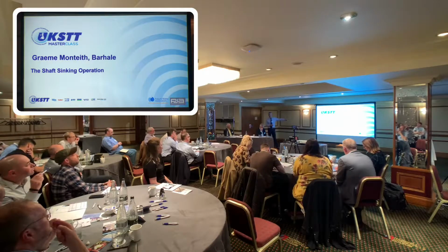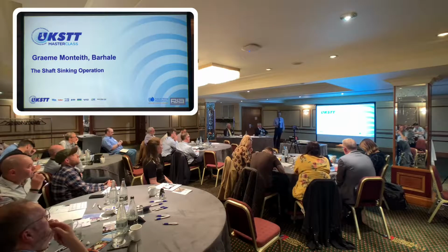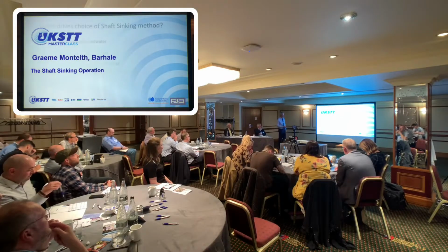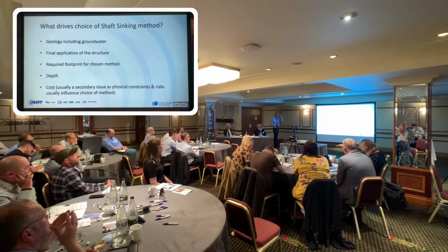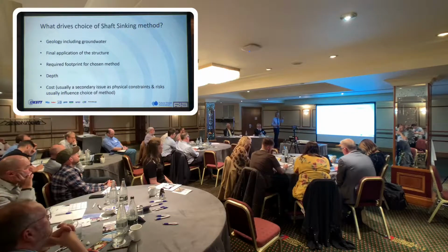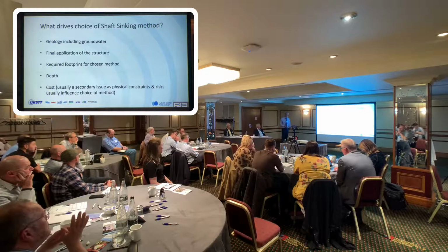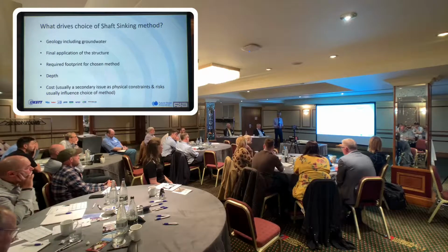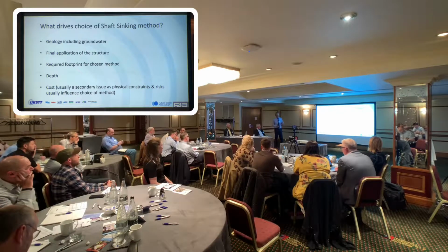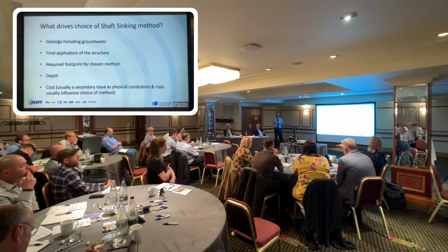And I guess if we could wait until the end of the shaft sinking section, I'll take questions on setup and the rest. I'm probably going to cover a few things that Jim's already been through on the design considerations. As we've said, I think we've majored on it all day: the biggest thing to consider is the geology and the groundwater regime on any site. The shaft sinking method that you choose will be heavily influenced by both of those things, along with the final application of the structure.